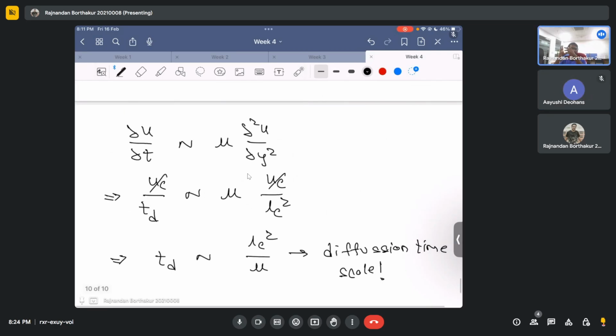Because honey is basically a very viscous fluid, the Reynolds number of such problems is typically very small, and that's why we will choose the diffusion time scale in order to accurately capture the essence of the problem.